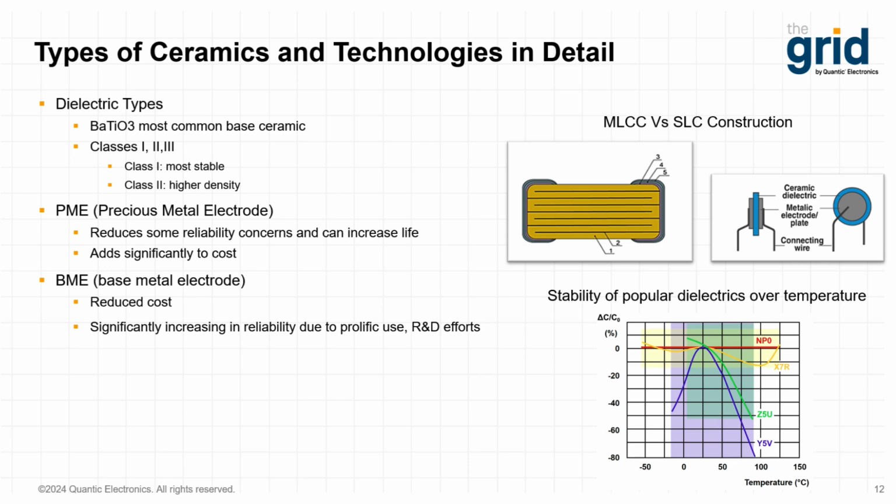As of today, lots of additional research has been applied to base metal electrode technology MLCCs. The reliability has increased significantly with these products, and they actually can now be approved to MIL-PRF-32535. So that can now be used for military, DLA, and space applications.